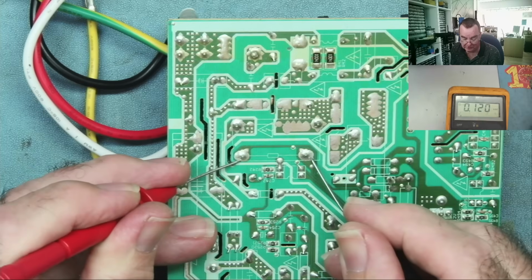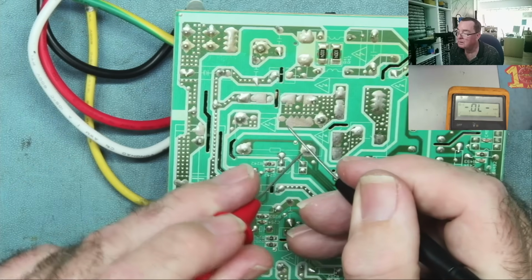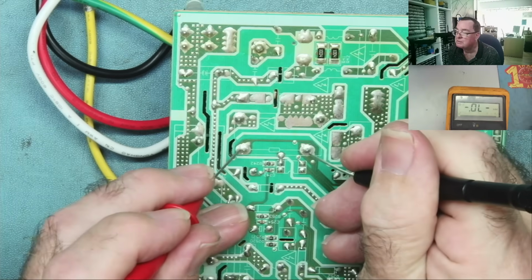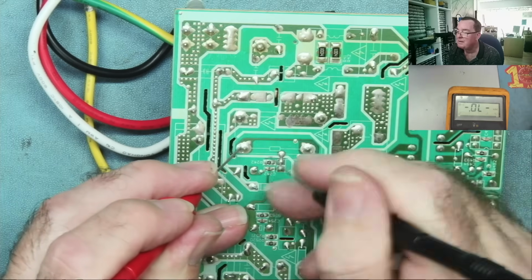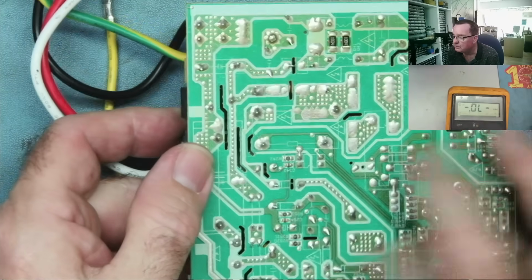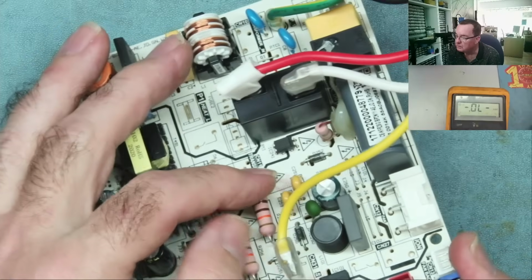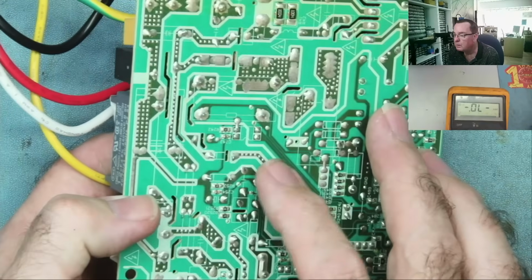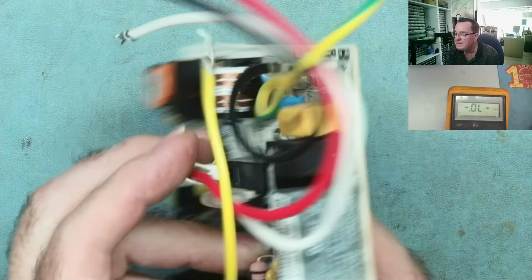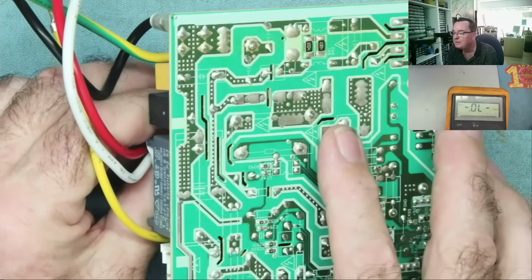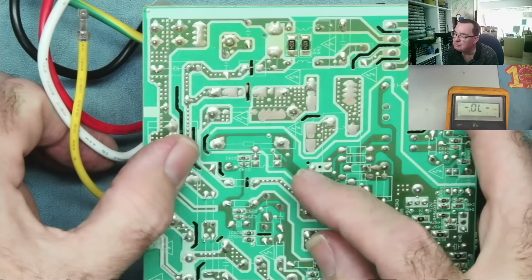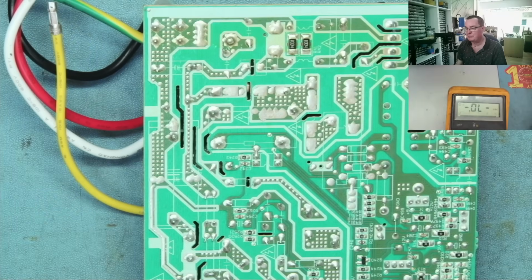But because of the resistance, there we see 120. And there we see 120. So because of the resistance of the coil, I can't actually determine where the diode is. And if I can't see it visibly either, that doesn't seem to go to there. Okay, so I can't really tell which way the polarity is to switch this relay. So to test the relay in this case, I'd be better just to take it out of circuit.